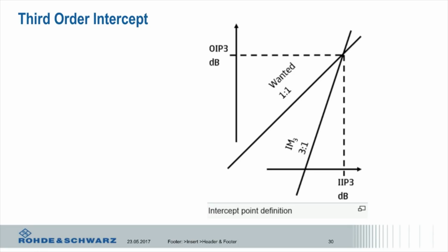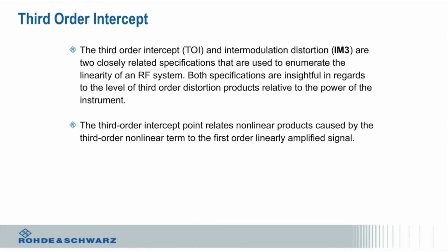Okay, so third order intercept, also called IM3 or TOI, the key thing here is when you put signals that are close together, it makes it very difficult to filter them out. When I was talking before about the mixer, you have to design a filter and carefully choose your frequency so that you can get rid of all those terms that you didn't want.